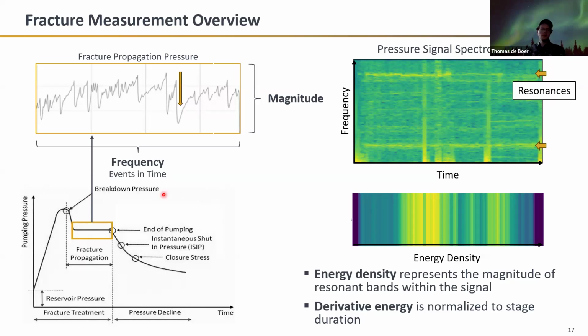As a typical, though, we have two main streams, one being those 1 hertz and the second being those 50 hertz. In regard to the typical resonant frequencies, I would say there is a broad range. Within our signals, we can see resonant frequencies anywhere in the very low frequency spectrum of sub 1 hertz, all the way up to 10 to 15 hertz for some of our more surface impacts.